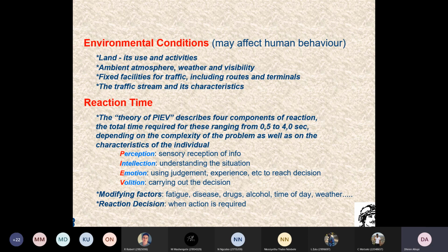So morning, you have your morning peak where you have high volumes of traffic. Your concentration is on the vehicle in front of you. The vehicle behind you is concentrating on you. So there's heavy flow conditions. Could even be unstable flow conditions where traffic is moving at fairly high speeds, but heavy concentration between drivers. Okay? And all you need is maybe a winter granny in that traffic proceeding to do her Pick n Pay shopping and reduce speed. That could have a ripple effect, and you could be then down to forced flow conditions and even a traffic jam situation where all vehicles are then stationary.